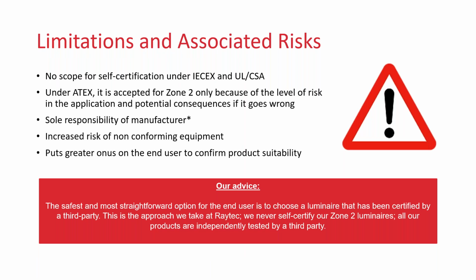So, things to think about when looking at self-certified product. Has the design been fully assessed against the requirements of the standard? Are they using the latest version of the standard? Some of you may know that Ex nA is no longer a valid protection concept and has been replaced by Ex ec.